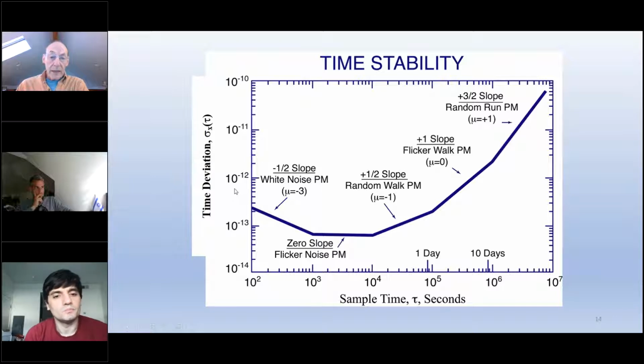So white noise in phase. This allows you to focus on the phase noise here, where you can see it going down. You can see these places where it changes. That's critical for any kind of filtering you're doing. If you're doing a PLL, you want to lock the PLL to where it stops averaging down, for example. So that's critical to know.